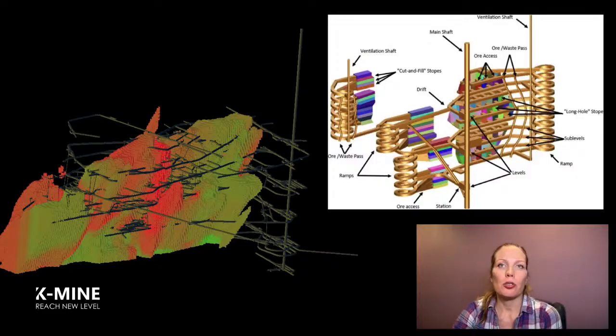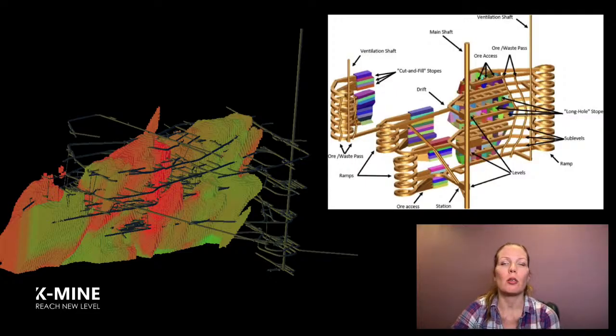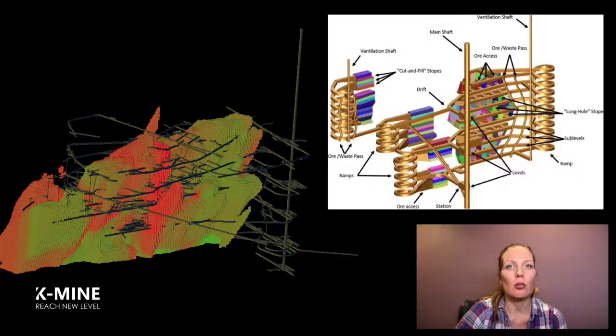Another important constraint at this stage is accessibility and routability. In underground mining, there is no point optimizing stopes in areas that can't actually be reached with an acceptable gradient, turning radius, and ventilation pathway. That's why we typically add an access graph to the geometric model representing levels, blind drifts, raises, and ventilation crosscuts.